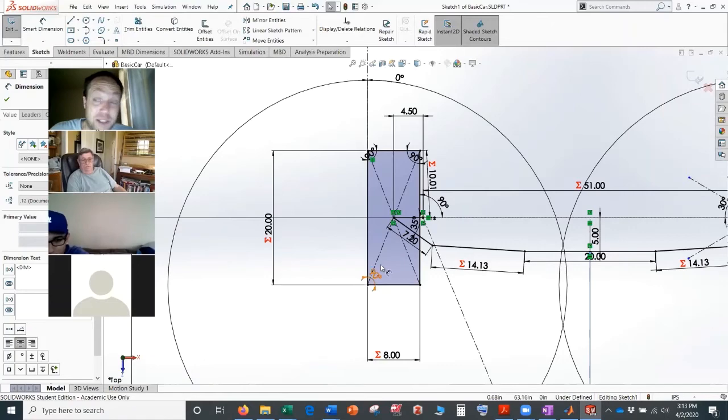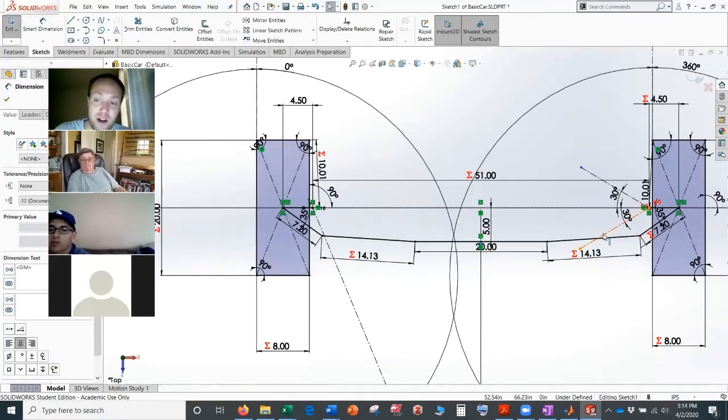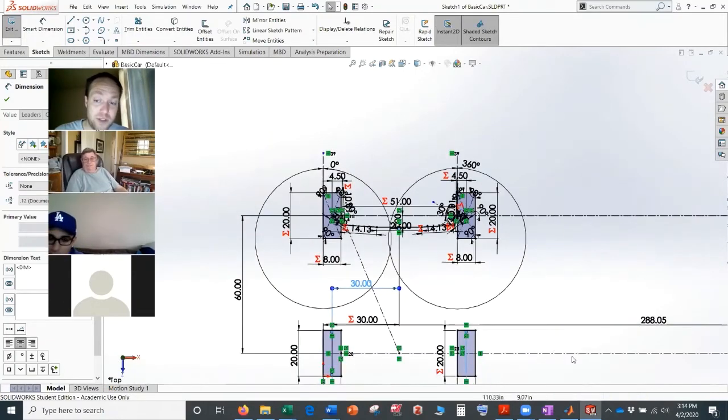Okay, keep in mind what you need to be careful of is, for example, your tie rod could also be hitting this arm. These have to go together in space. Usually this is the bottom arm, it's below, and the upper arm is above. Then you also have a shock or a push rod in here somewhere. So you're tweaking all of this geometry, looking for what's limiting you. You're trying to get the inside wheels to turn as much as possible, but you also want them to converge on this line, so you're getting Ackerman.